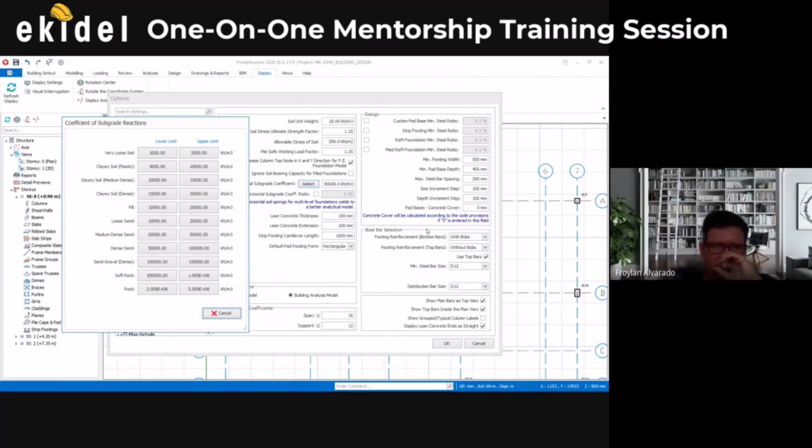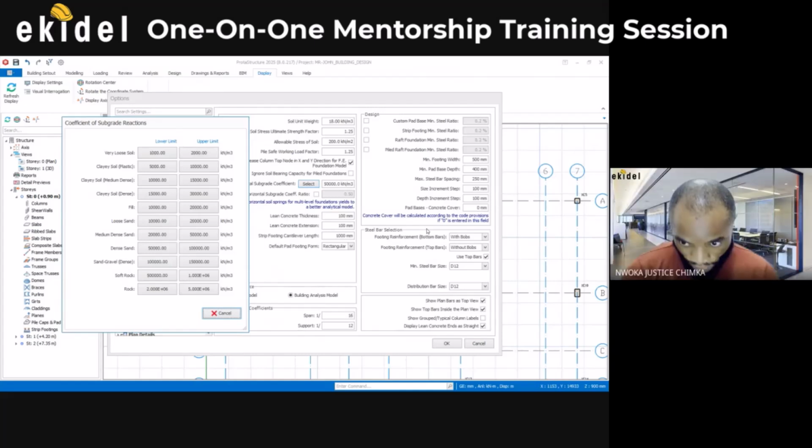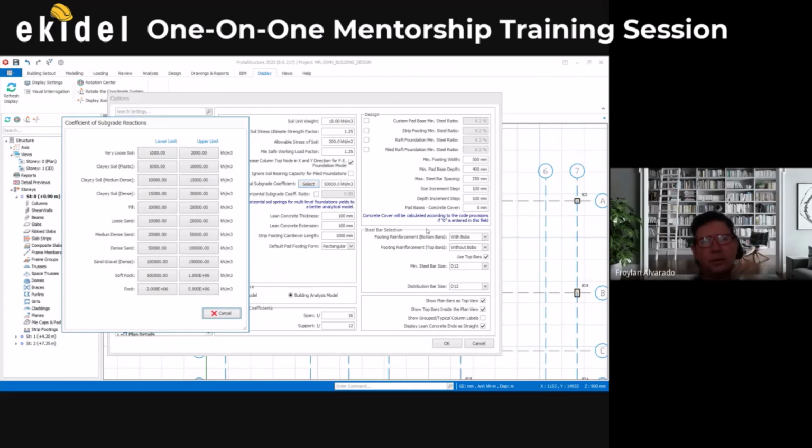So if you see each pile, one pile can bear, say, 90 tons, no? Yes, I can see that. So whenever you're designing the piles, you can say, all right, you know what? We don't go with those numbers. We go with far less than that. So we usually would say 90 bearing capacity. We usually bring it down like 30% less, no?